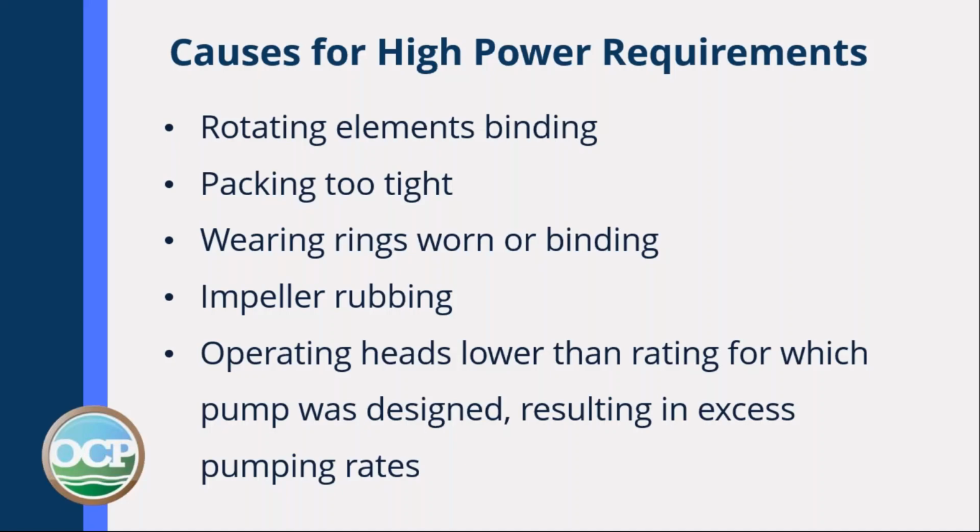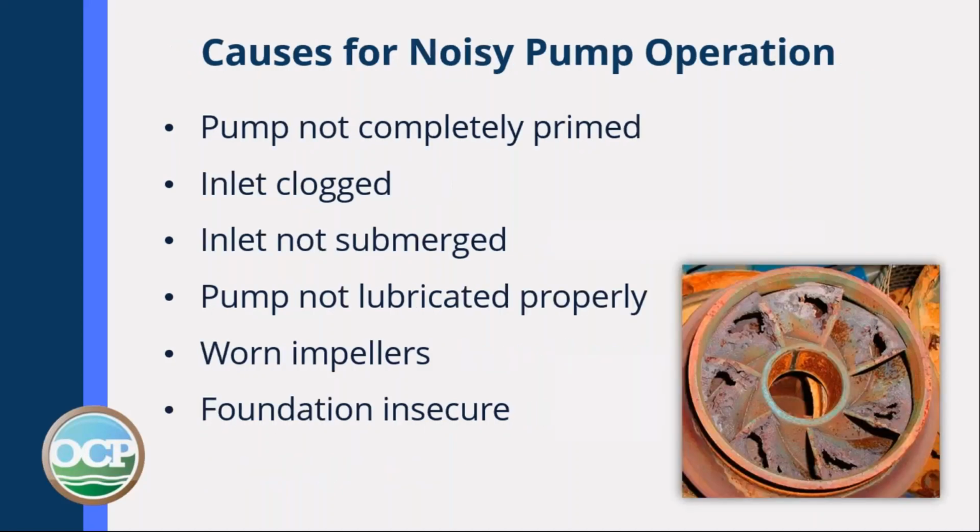Operating heads are lower than the pump is rated for, resulting in excessive pumping rates. For noisy pump operation, maybe your pump is not completely primed. Maybe the inlet's clogged. The inlet's not submerged, so you're pulling air. The pump is not lubricated properly. You're trying to pump with an impeller, like the one in the picture, that's worn out.